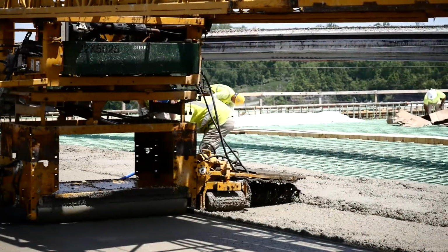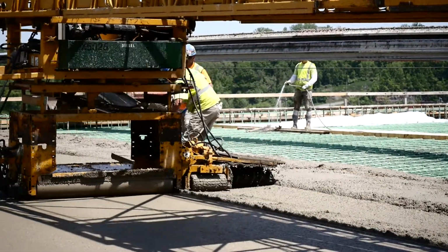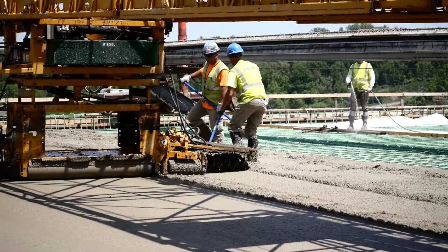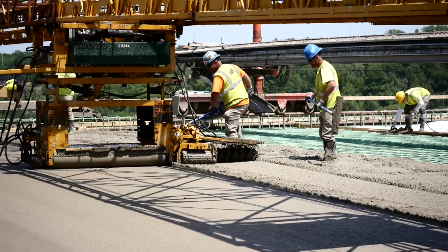There are also issues if material like this does end up out on the project. It can result in premature failures such as cracking. You can get spalling out on bridge decks, and you see a lot of visual issues as well as some structural components that you might not see immediately, but you can see down the road.